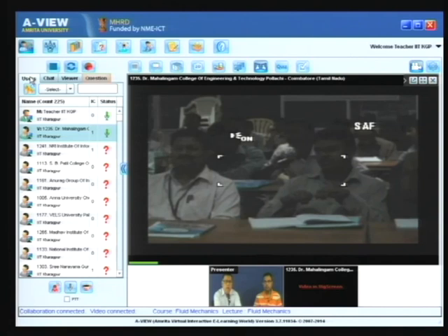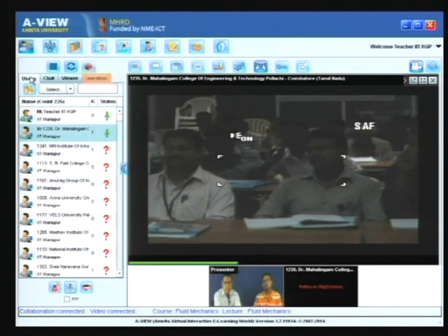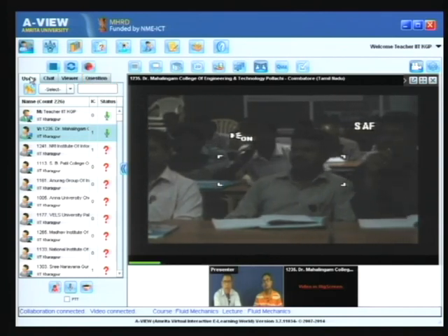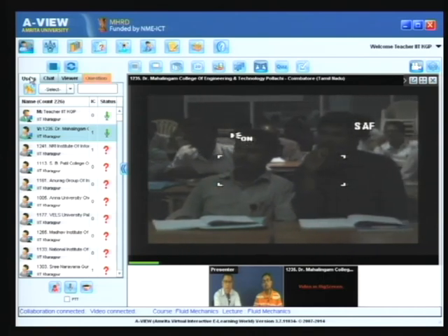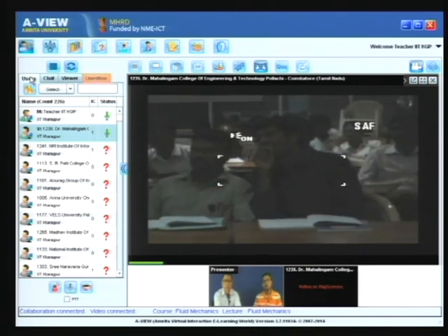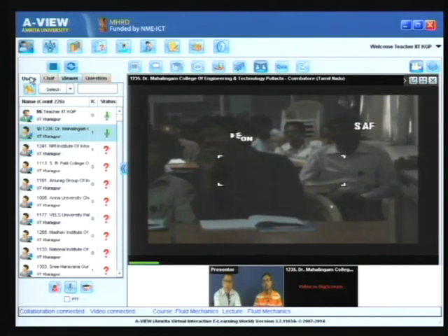See, you would like to have the downstream pressure tap as close to the vena contracta as possible, because then the curvature of the streamlines will not affect your measurement. However, that will depend on the Reynolds number, and you cannot really put it exactly at the vena contracta, because you are going to use a device for measuring flows of different flow rates, and you can't keep shifting it.